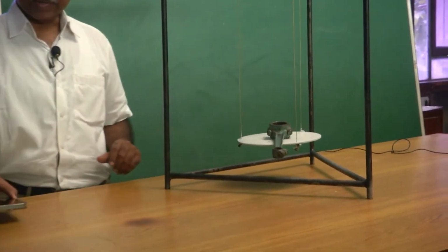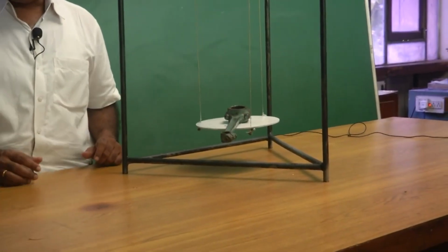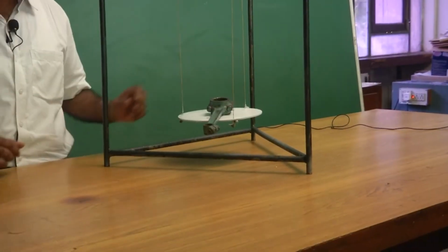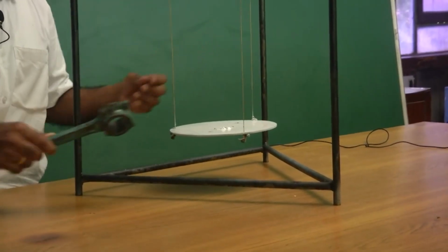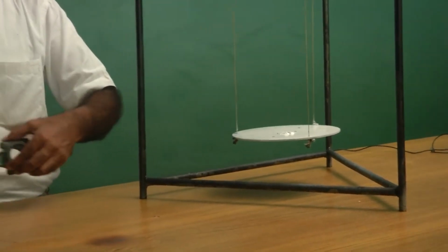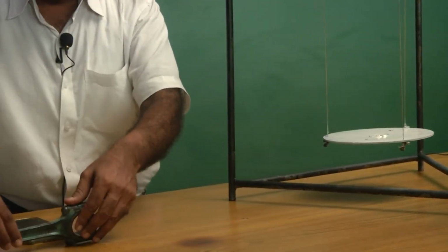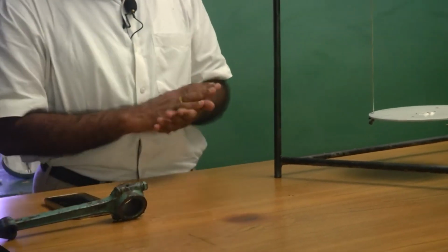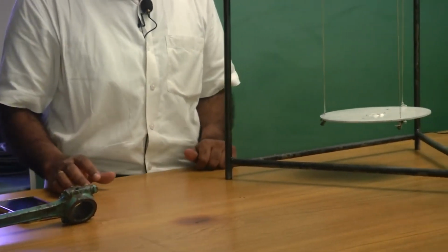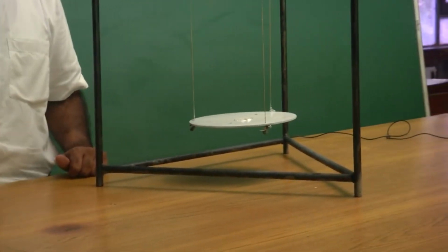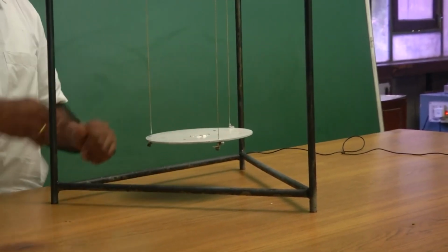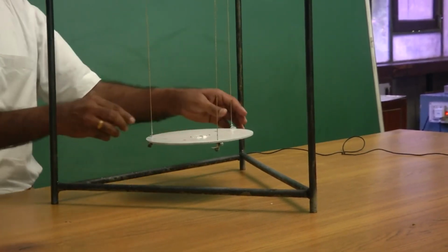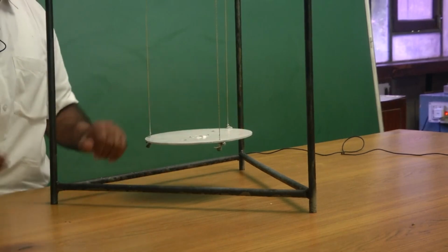So, the period for 10 oscillations is 11.9 seconds. A larger number of oscillations will help us in reducing the error in the measurement, but that is how we record it with the connecting rod in place, and one set of measurement can be done without the connecting rod. So, I can keep on taking another set of measurement for only the plate in place.